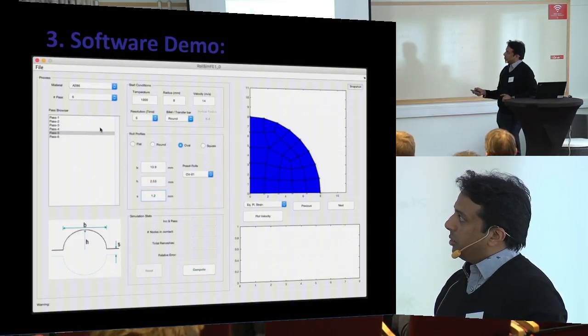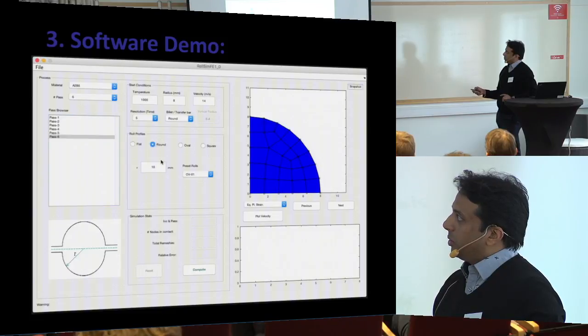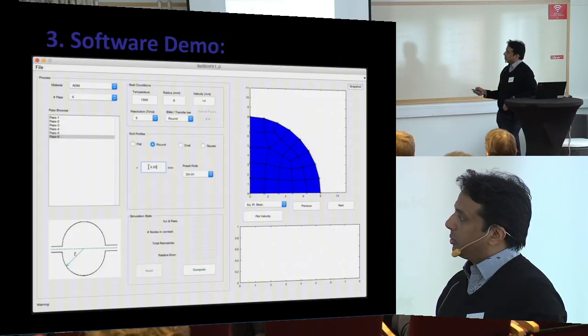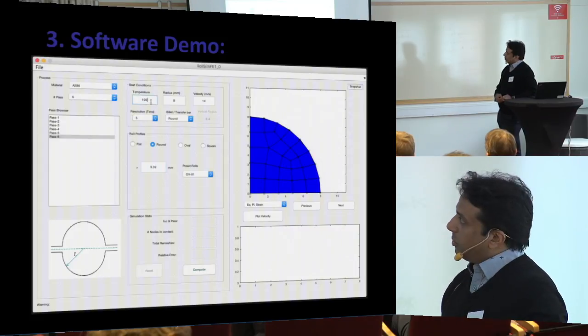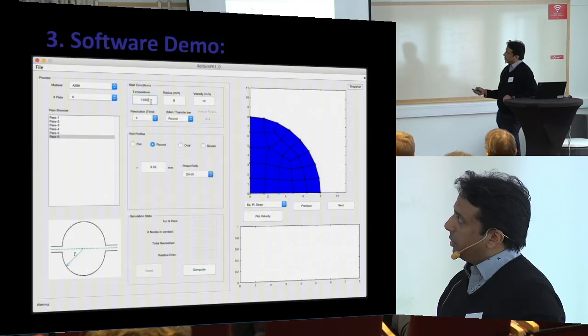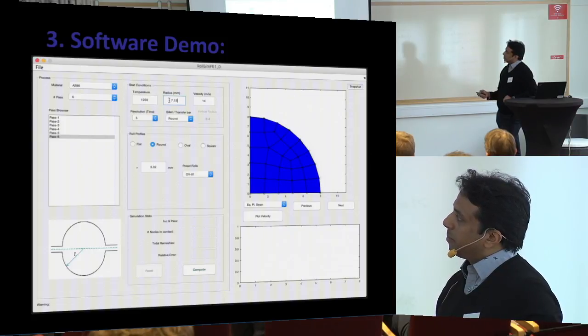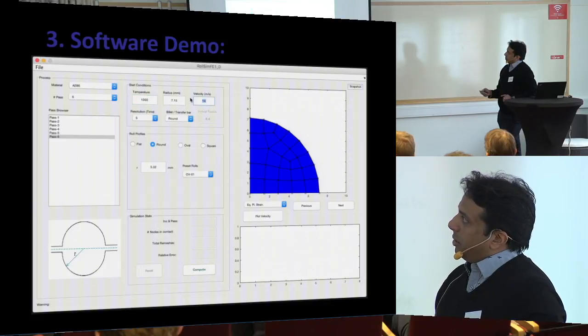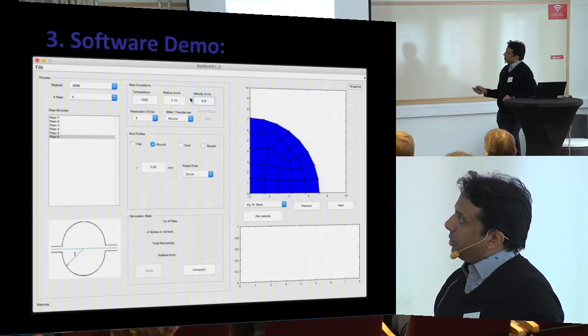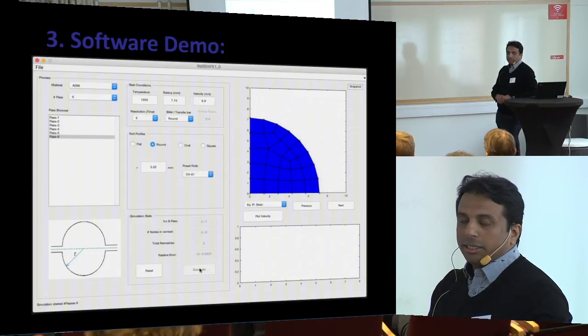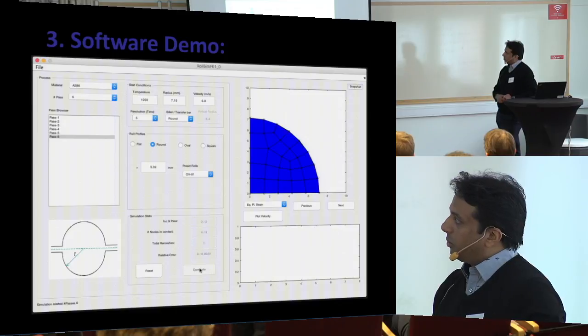It's only entering process parameters and selecting the material. We have the possibility of different tools. Here what you see is alternately oval and round, but you also have flat rolling as well as square tools included. And here you see the initial properties, that's initial temperature, initial radius of the wire. Here is the ingoing velocity. We have the possibility to give different initial cross sections, typically round, oval, or square.